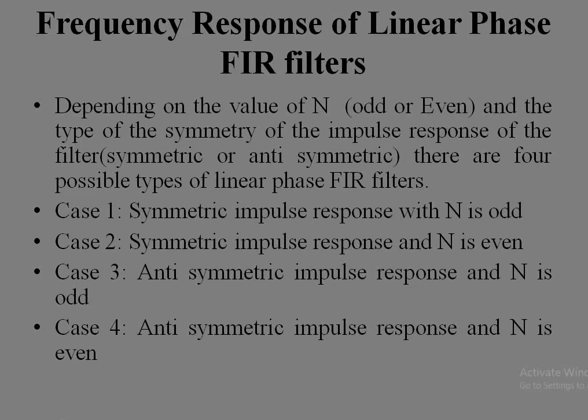Depending upon the value of n, that is the number of points in the impulse sequence, whether they are odd numbered or even numbered, and based upon the type of symmetry of the filter's impulse response, that is, either symmetric or anti-symmetric, there are 4 possible types of linear phase FIR filters.